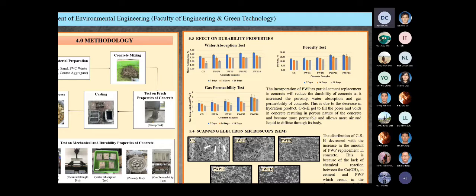So I record the bubble travelling from this distance to this distance, how many seconds. And then I put this time into a formula and then calculate the porosity.